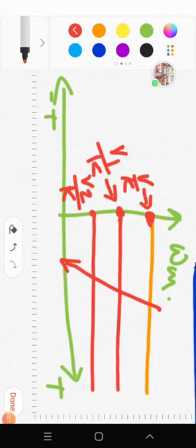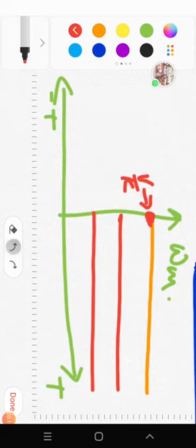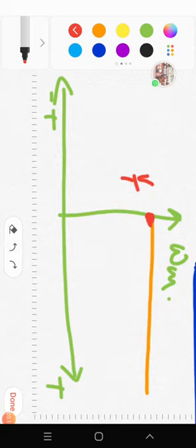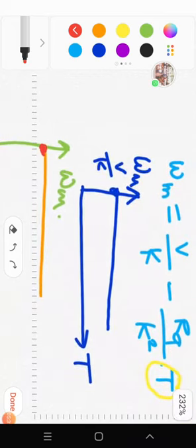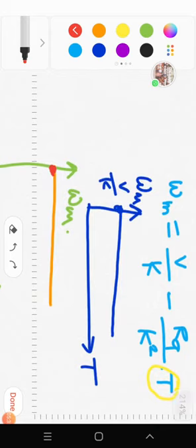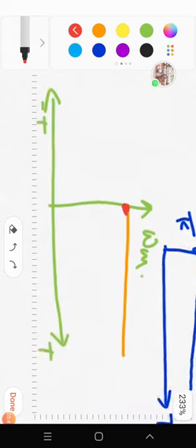So even though there is, you can say, reversal of the torque, negative torque, even in that case the same characteristic equation works, because there is no change. If we substitute negative values of T in the same equation, slope will still remain negative, y-intercept remains same.